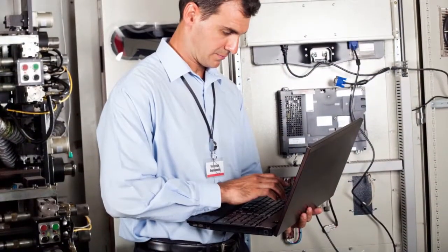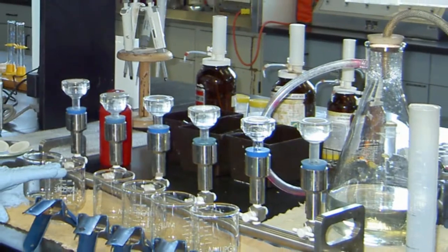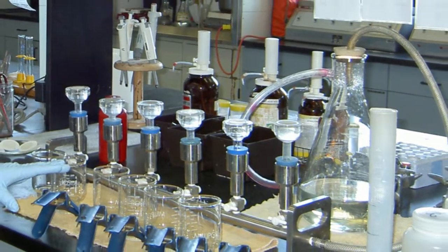We remained on site for a few weeks. Settings were adjusted according to lab and field test results to consistently achieve the best quality effluent possible. However, several equipment problems were discovered during these studies that eventually had to be addressed by the owner. The motive pumps used for both mixing and aeration were consistently plugging. Once plugged, any success at a quality effluent was impossible. The pumps were eventually replaced with grinder pumps, and we were on our way.